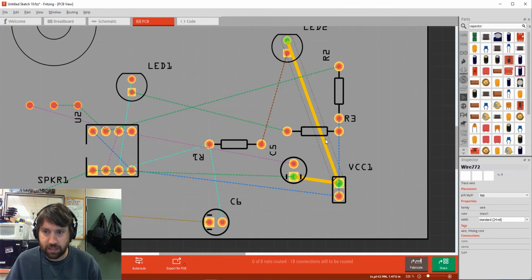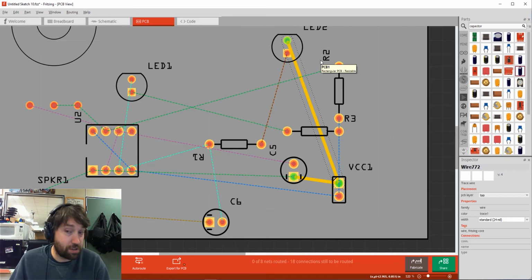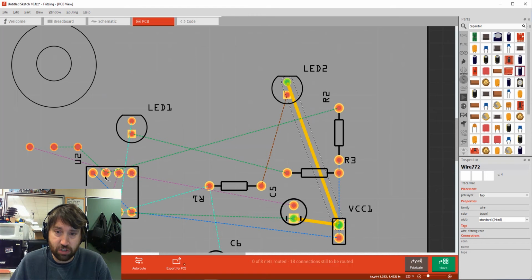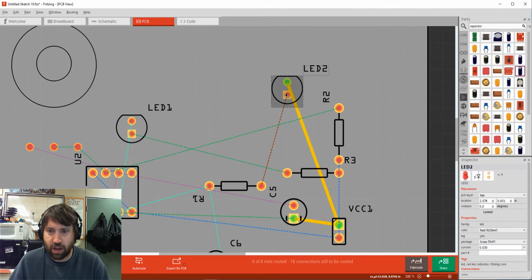Now this trace is still a little bit suspect. It could travel underneath the resistor itself, because that's not where we're soldering it in. But it would interfere with a wire that we have yet to make here. Although whether or not we want to do this actually just depends on how we're going to solve the problem. Right? I could run this trace outside here. So this may not be actually the worst solution, but certainly I don't like how close this is. It's running over top of the pad. So I might rotate this a little bit to free things up.